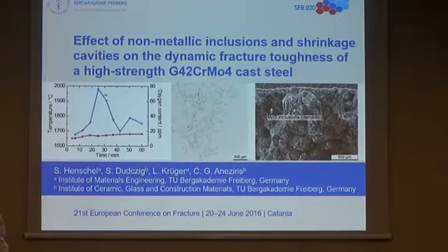And when we have a look at the deformability, the elongation at fracture, and the reduction of area, we can see here that specimens from the top of the cylinder had quite a high elongation and deformability, but specimens from the center and from the lower part of the cylinder had a lower ductility, which also causes a lower strain hardening, which is seen here by the lower ultimate tensile strength.